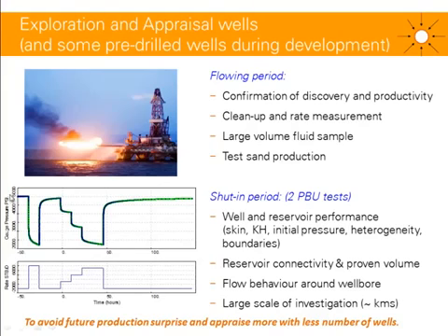So here at the bottom left, I've shown you a standard well test in the exploration appraisal context. So first we will have a cleanup, which lasts in some cases between 10 to 24 hours. The first PBU, then in some cases a flow after flow test, a main flow period, and a second PBU. In general, it's better to have 2 PBUs so that you can QC the response and you can investigate for deconvolution. Deconvolution is a new tool and we're going to see this later.